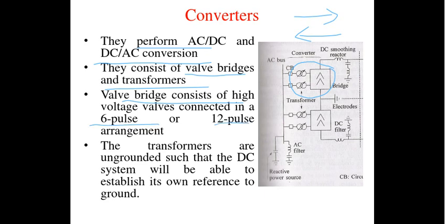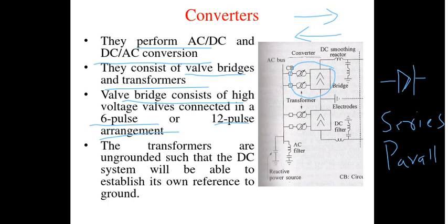The voltage and current ratings of the SCRs are selected in such a way that it may sometimes necessitate the series or parallel connection of the valves in order to meet the required rating of the power to be carried in the transmission line.